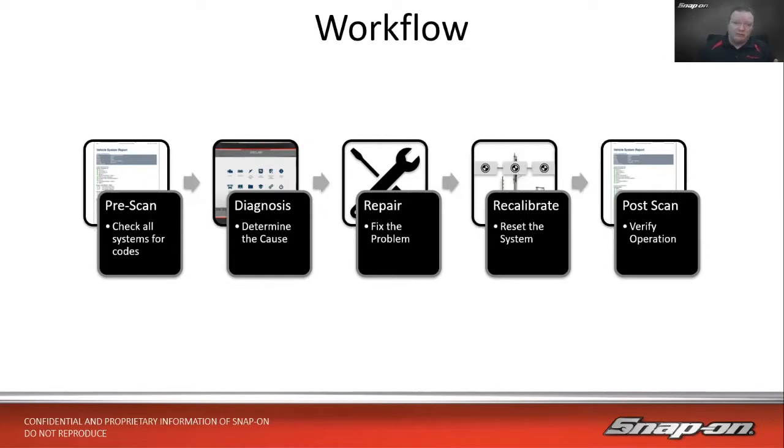And it's not just for things you might think of, say, ADAS, right? Just about everything needs some sort of a reset or relearn or calibration. How about an oxygen sensor on a GM? You have to reset the heater circuit. How about any host of other things? If you're here right at the very beginning, we looked at that Evap monitor test, right, to make sure that Evap monitor runs. So any of those, you might need to do a recalibration, a reset, a relearn, and you have to look up and find out where that happens to be, right?